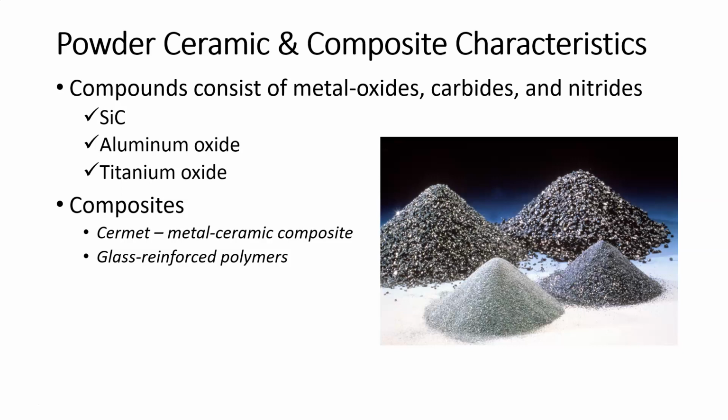Now with powder bed fusion, we have kind of all of that. We have the thermoplastics, and we also have an enormous range of metals, plus these very excellent compounds and ceramics that are used in tooling to make very strong, very heat resistant parts. And so there's a lot of interest in powder bed fusion because of this wide range of materials.